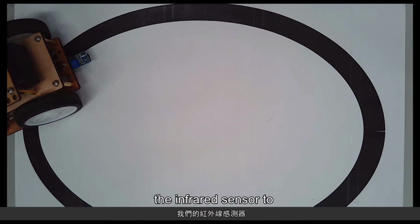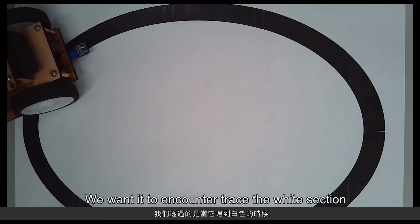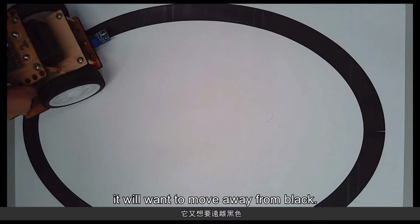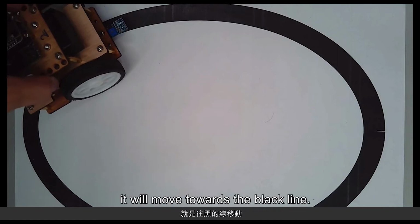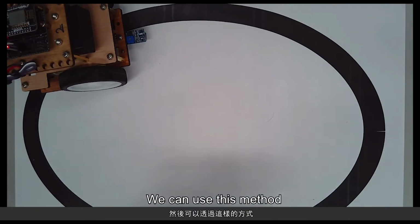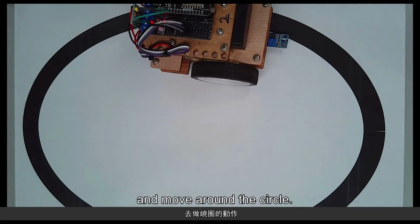We will set the infrared sensor to perform a tracing action inside the black line. During the tracing, you can see that the infrared sensor is located here. We want it to trace the white section and look for black. When the infrared sensor traces black, it will want to move away from black. It will continuously use this method. If it's white, it will move towards the black line. When it is on the black line, it will move in the direction away from the black line. We can use this method to trace the black line and move around the circle.